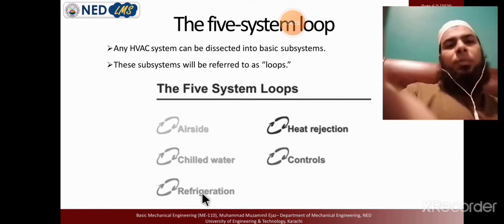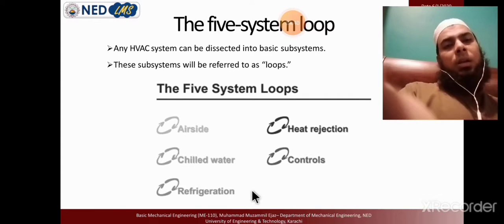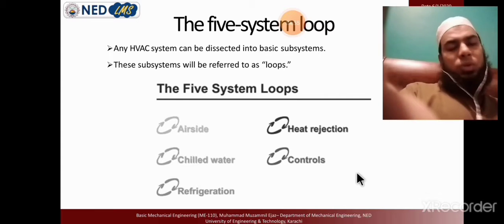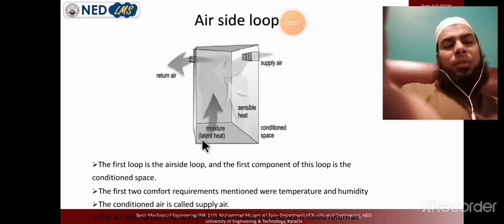And similarly, the refrigeration circuit also needs to reject heat. The rejection of heat is done by the condenser, just like the outdoor unit. If it is a rooftop unit or package unit, it directly rejects heat to the outside air. But in the chiller, it is basically not done by air only. It first rejects heat into water, that heat rejection circuit, and that water goes to the cooling tower, and the cooling tower reduces the temperature of the water.